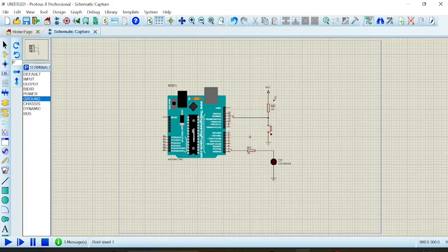So pin 12 of the microcontroller is constantly low. But when you press the push button, the pin will change state from the low state to the high state. Here we focus on the pull up mode. So we are good to go.